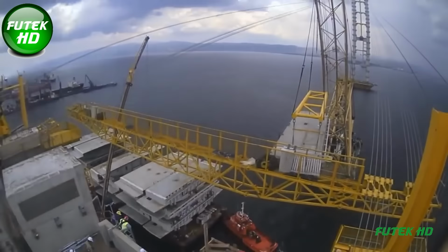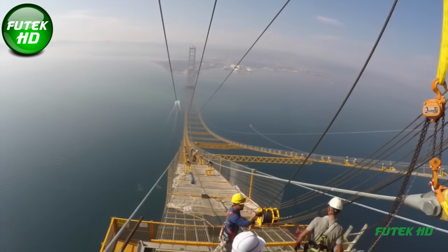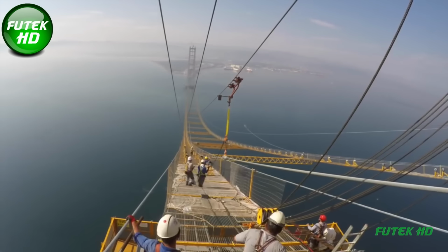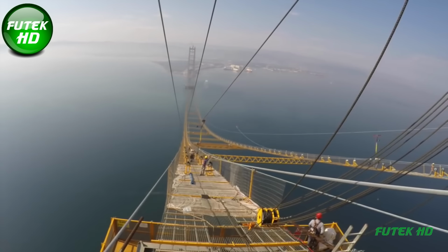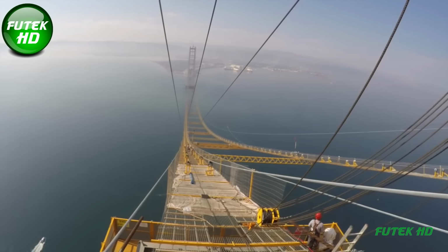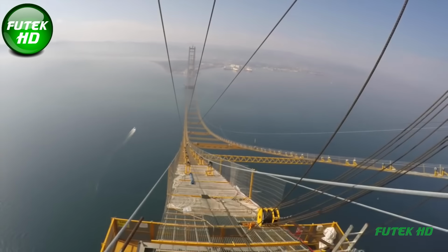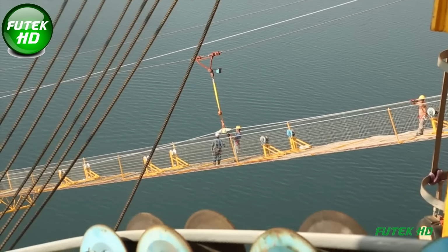Near the main towers, the blocks were lifted with the 1,200-ton floating crane. For the majority of the deck, however, a lifting device was installed directly on the main cables, allowing sections to be lifted directly from barges beneath the bridge. This dual lifting strategy allowed for simultaneous work at 4 locations, accelerating the process to install roughly 2 kilometers of stiffening girders in just 3 weeks.